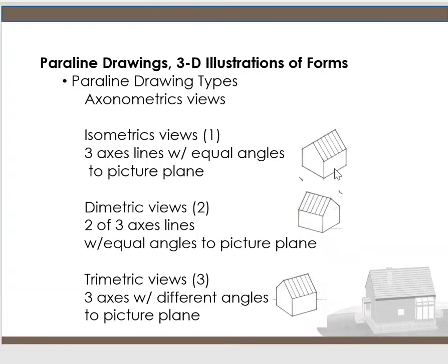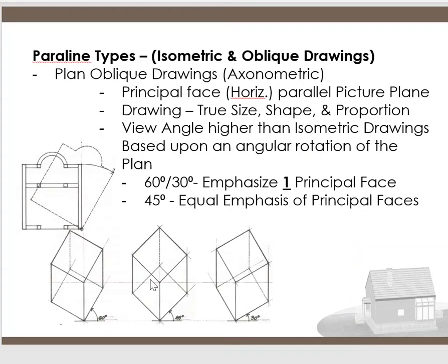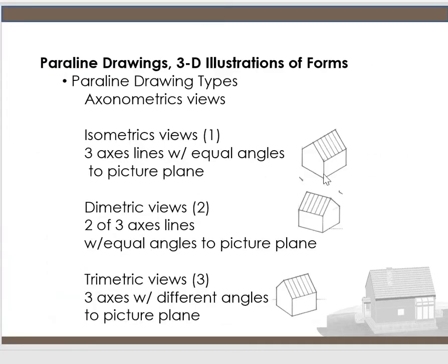So as you can see, it's different. See this drawing, than perhaps something that's very tilted. That's why this plan oblique is more tilted, where this is more subtle. Okay, it's a little more subtle. It seems a little more grounded. So remember, ISO is one angle. They're all equal angles. A dimetric has two different angles, and a trimetric has 3 different angles.